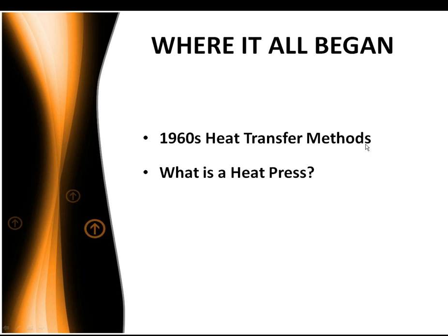The different chemical properties required to make a productive adhesion onto those fabrics are very important, but the key to all of that is having a heat press that will give you accurate time, temperature, and pressure. And those are some of the things we're going to talk about.